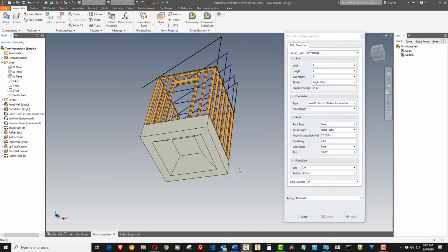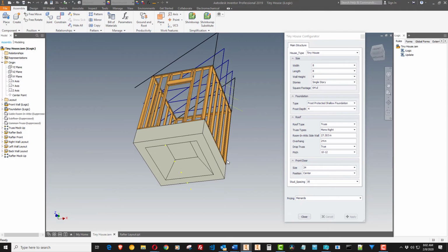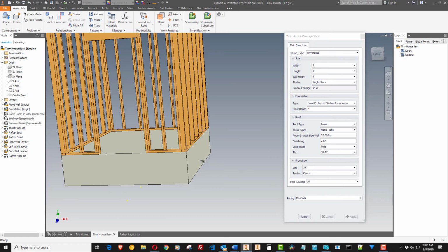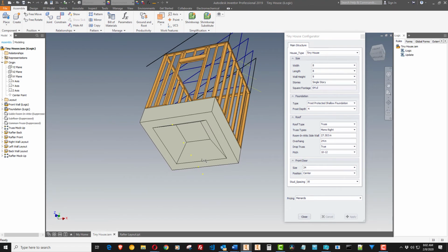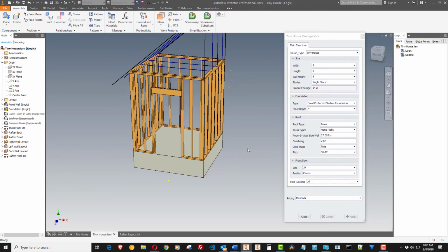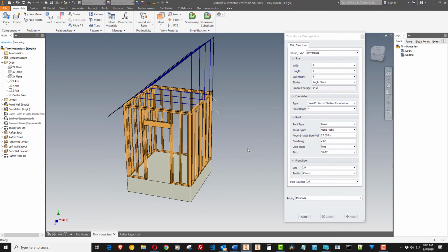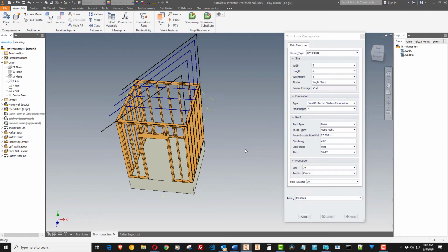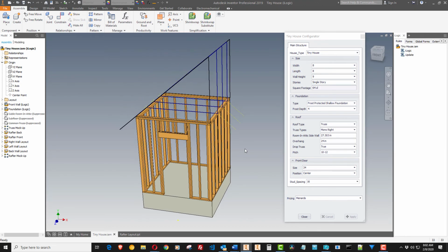I'll probably make an entire video explaining how this works, but it has 2-inch insulation coming down the side, and then it extends out into the dirt. And what that does is traps the earth's heat underneath the slab and won't allow it to heave. Heaving is why you're not allowed to build on a slab in this kind of climate, because it will lift up part of your house and crack it, and it'll basically destroy your house.